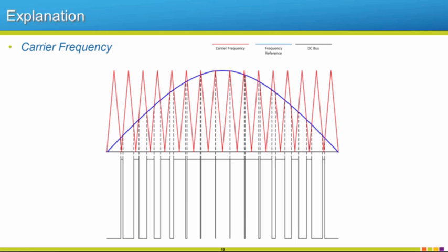That's just the actual vibrations in the laminations that make up a motor that we talked about before. Remember that the stator has those little chunks of iron broken up in between there, and that's those laminations kind of vibrating and making that noise. Now, as you increase your carrier frequency, you're going to notice that that noise kind of goes away. Well, it's just because it goes to a higher frequency that you can't hear, or that I can't hear anymore anyways. So that was a good question. So there's carrier frequency.